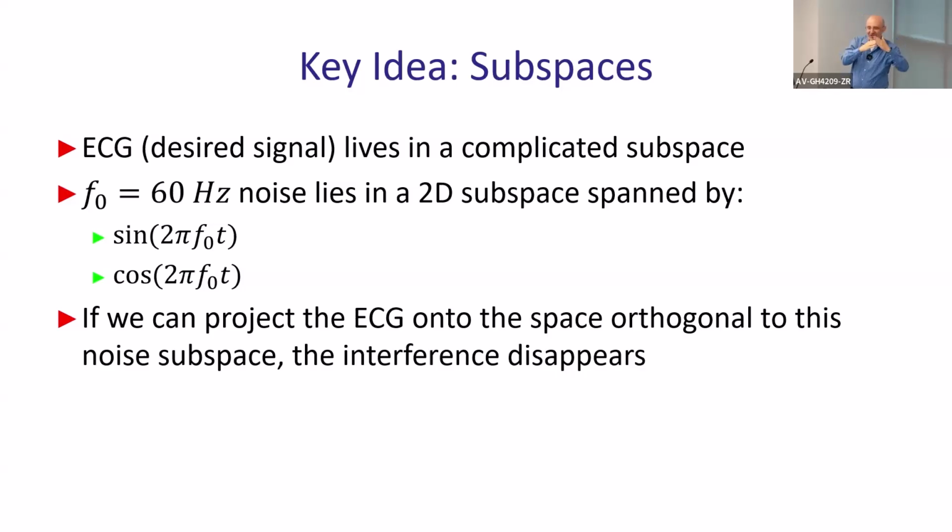So you're dropping it into that subspace to get the closest result. You have that subspace, whatever complicated subspace of signals, and the noise is orthogonal to that signal. So project it to your signal space, and you will get only signal. You will not have any noise. This is the overall idea, okay?